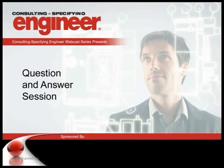Okay. We've got time for one more question or comment, and we're going to take it from Mike Wysocki from Michigan, who's saying Article 705.16 indicates that, quote unquote, consideration shall be given to the contribution of fault currents from all interconnected power sources for the interrupting and short circuit ratings of equipment on interactive systems and includes generators.